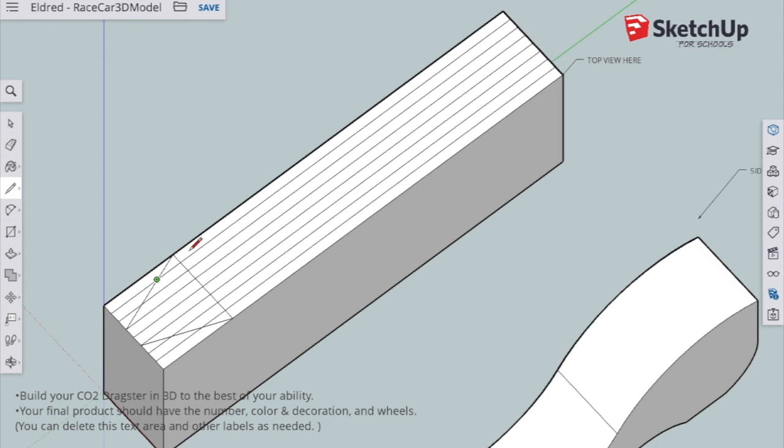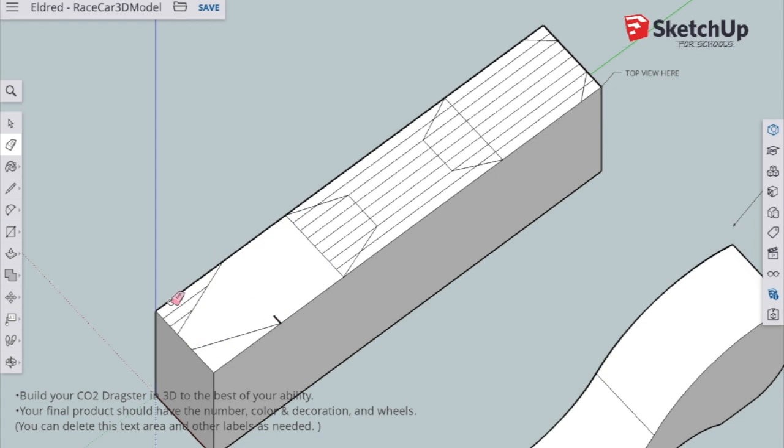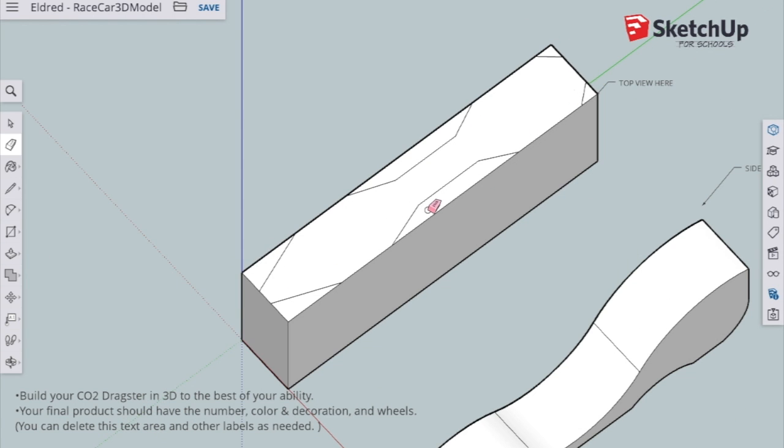And basically setting up this geometry lets me make this shape symmetric based on this centerpiece, the center line, which is the midpoint. I'm going to delete a bunch of this stuff out and then use the push-pull tool to push this out and then combine the two tools. Let's see how this works. Okay, so now I can use the push-pull tool to push this all the way out.